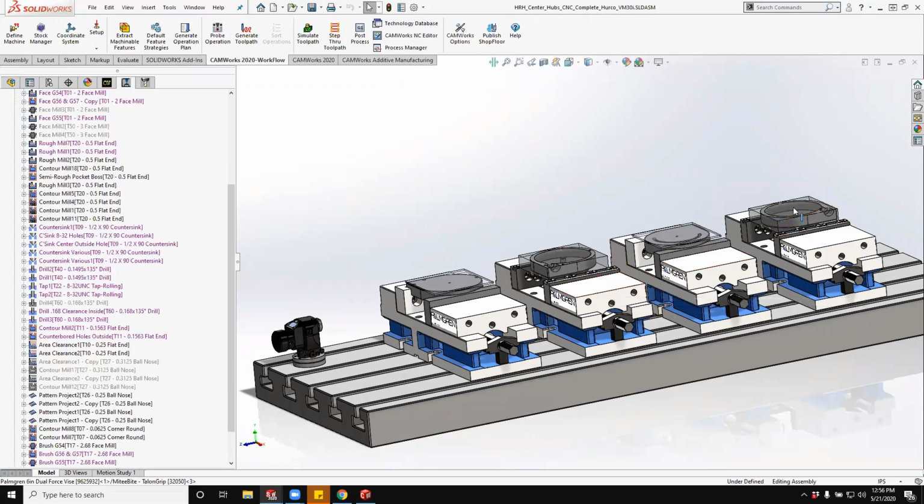And so Brian jumped in and put his own safeguards in so that it's looking at the heights of the next setup before it starts to move over there. And he does similar things with making sure that the spindle's running before you start moving the machine. And so there's a lot of safeguards that we put in. And so even though we charge a little bit for our posts, we think in the long run that you're getting a much safer post and it's much less expensive than crashing a machine.